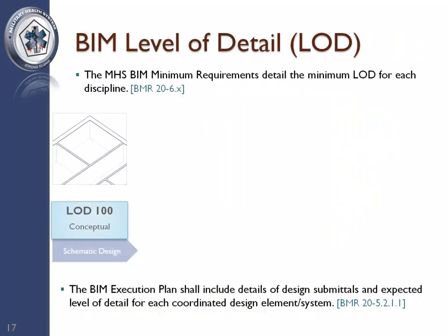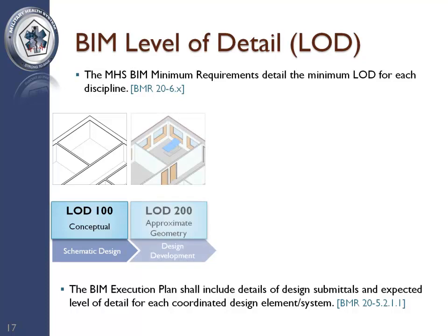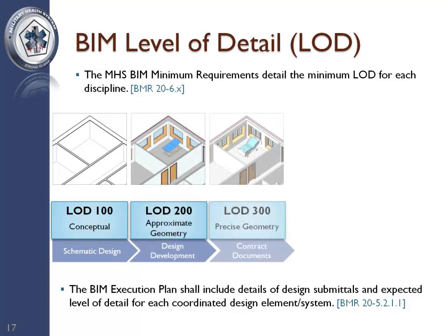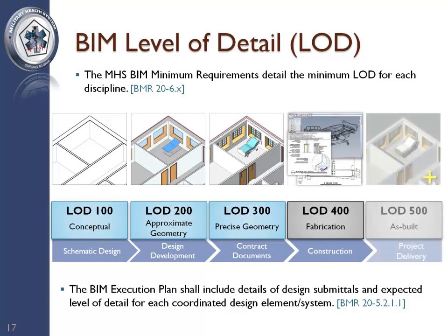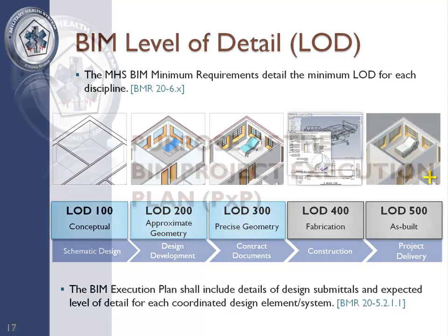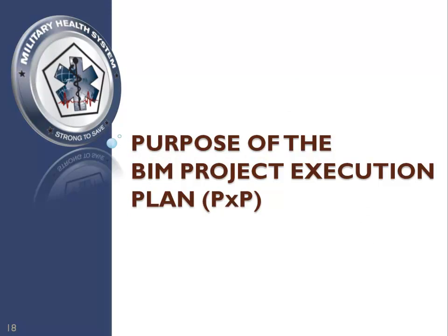Another important concept is Level of Detail, or LOD. This refers to the completeness of BIM data. The MHS BIM minimum requirements specify the minimum LOD required for project models. At the concept stage, LOD 100 objects may be quite generic. After LOD 300, it is common to supplement the BIM model data with data in other formats from consultants, subcontractors, fabricators, or manufacturers. The total body of information, at LOD 500, is delivered at project turnover to the owner-operator. The BIM PxP is the government's tool for verifying that MHS BIM requirements are satisfied.